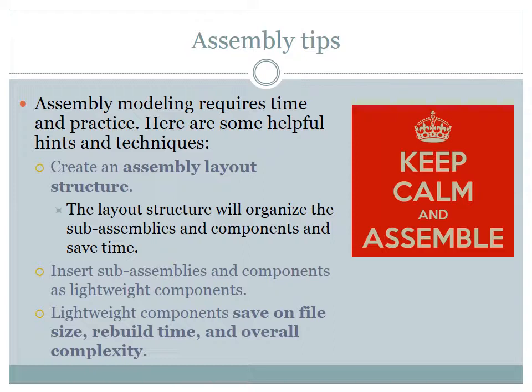Create an assembly layout structure. The layout structure will organize the subassemblies and components and save time. Insert subassemblies and components as lightweight components. Lightweight components save on file size, rebuild size, and overall complexity.